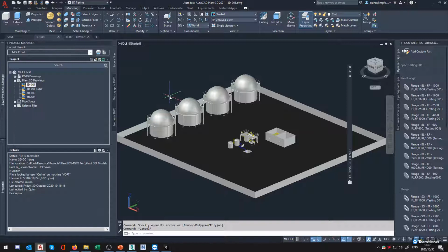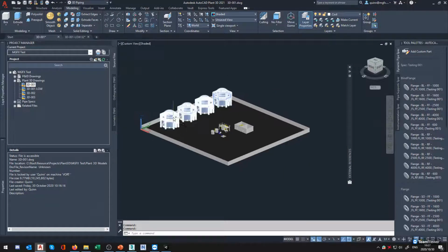A big mistake that a lot of people make here is they sometimes install Navisworks and then AutoCAD, and it hasn't put the plugin into it, and that creates issues, to say the least. Because the thing that we're going to do to get this drawing out is we're going to use a command called NWC out. Now, if you've installed something like Navisworks first and then AutoCAD Plant 3D, you're not going to have this command available.